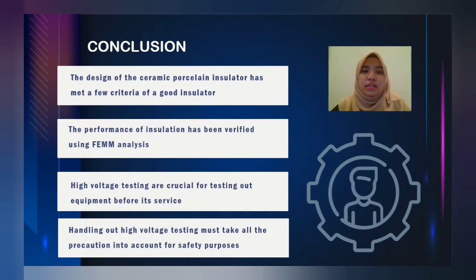Next, high voltage testing is crucial for testing equipment before its service. This is because equipment such as transformers and also insulators need to be able to withstand normal and abnormal high voltage before we put them in the transmission line. And also we follow the standards of the IEC and also the IEEE to do the proper testing of the equipment before putting it in the transmission line.